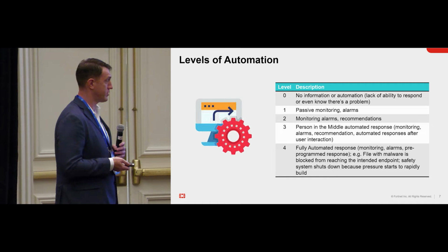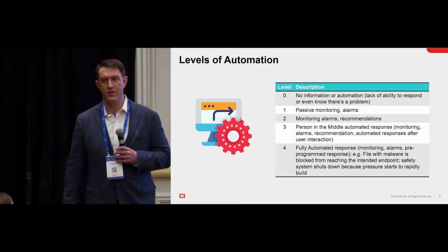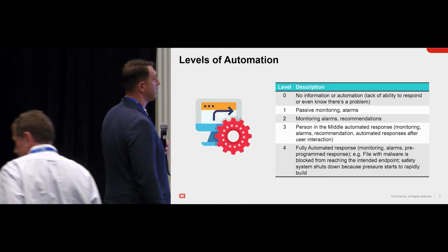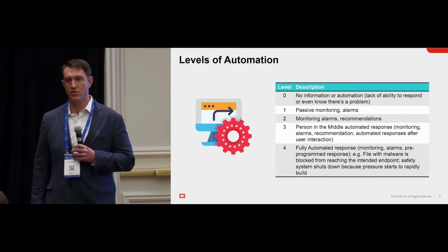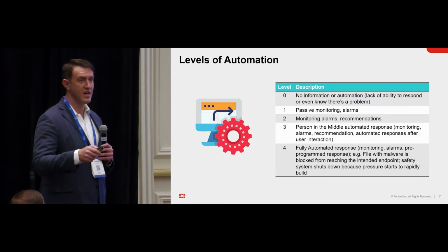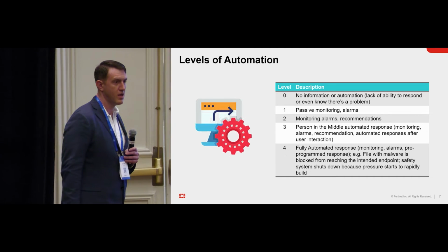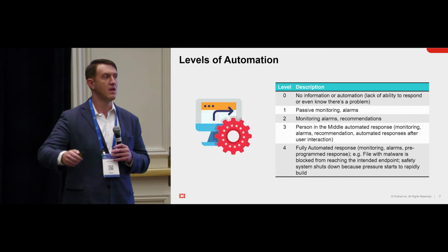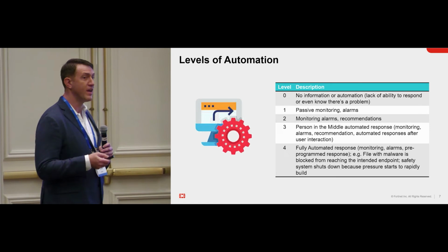And then you have the fully automated response. I have not seen anybody do this. We were talking to a vendor, an OEM, and came up with an example of what fully automated would look like. I have a DCS system that has 2 HA controllers. My primary gets compromised. I recognize that, kick over to my secondary, and quarantine the primary, and I prevent that secondary from talking to anything that's not a part of its DCS system, right? That's just an example of where some of the OEMs are looking to move to.